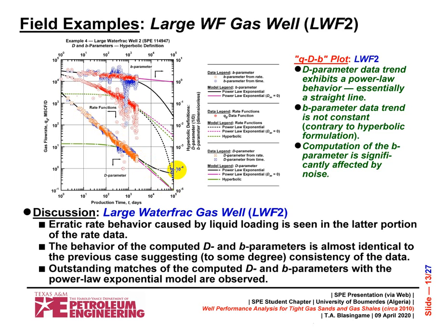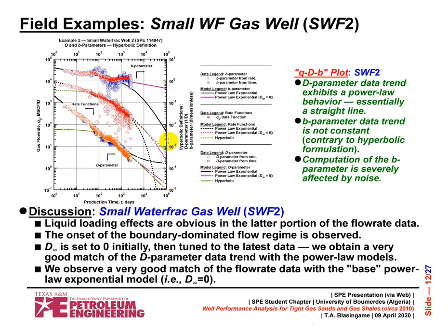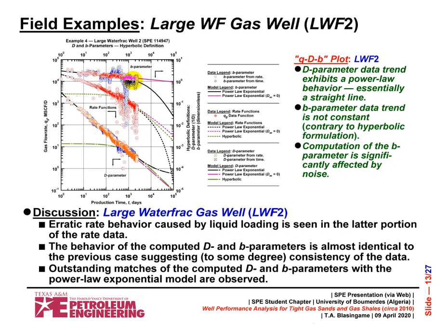And I'm probably not making this very clear, but what this tells you is that for almost 5 years, you're still at a very high B factor, well over 1. And being over 1 with your B factor tells you that you're definitely in transient flow. So this particular well, we believe, is still very much so in transient flow, as we did for the other one as well. There does appear to be some stabilization around a B factor of 1 for this case, so that could be evidence that it is trying to have a terminal decline.